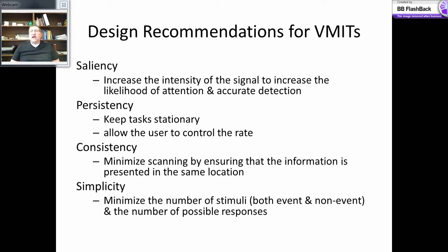Consistency is similar, but consistency is basically saying, if I'm going to be inspecting 3 welds, I want to be able to pick up the part, spin it around, set it back down, and always have it in the same orientation, right? I'm looking for the welds in the same point. They always start and finish in the same place, so that I always look for where that happens so I can recognize them. It's not some hodgepodge random Rubik's Cube situation where I have to treat everything differently.